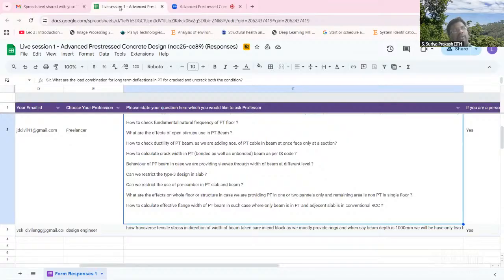Point number one, right? The second is when you are doing the calculations for strength at ultimate, it doesn't matter, right? So effective flange width still will hold good, because the ultimate condition is only one time that you are doing. It's a failure condition, right? So at that condition, a lot of redistribution of stresses would have happened and they will act as one unit, the slab and beam together, right?